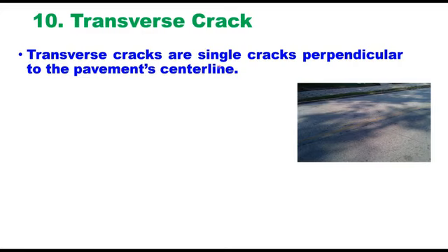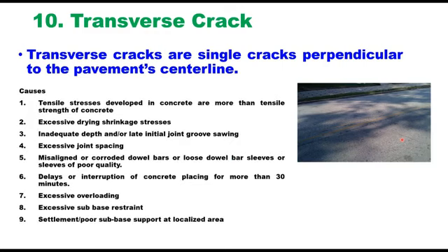Next is transverse crack. Transverse cracks are single cracks perpendicular to the pavement center line. And reasons for these cracks may be many. Tensile stresses developed in concrete are more than the tensile strength of the concrete. Excessive drying shrinkage stresses, inadequate depth, and or late initial joint groove sawing, excessive joint spacing,